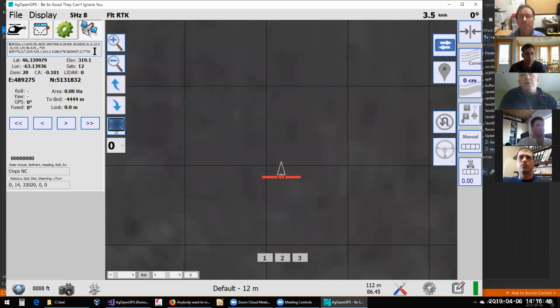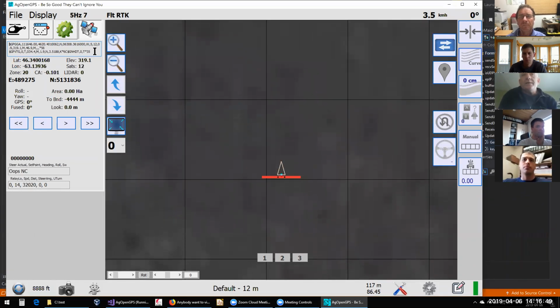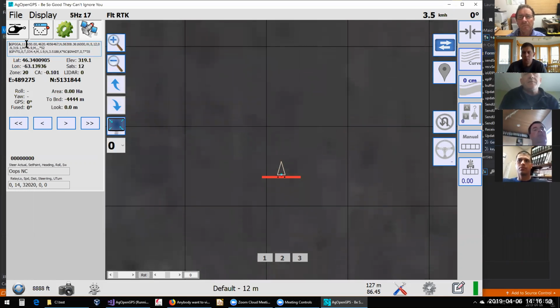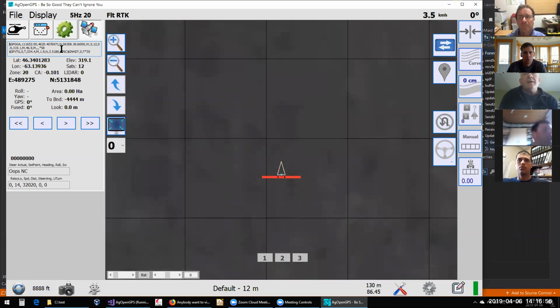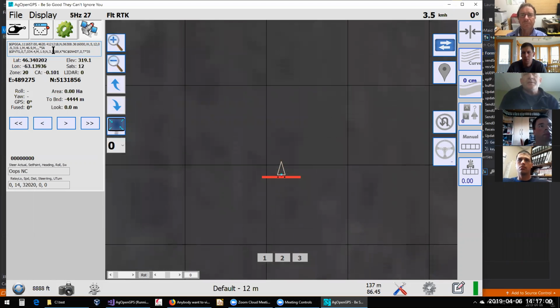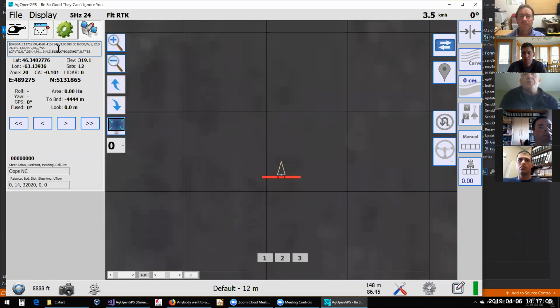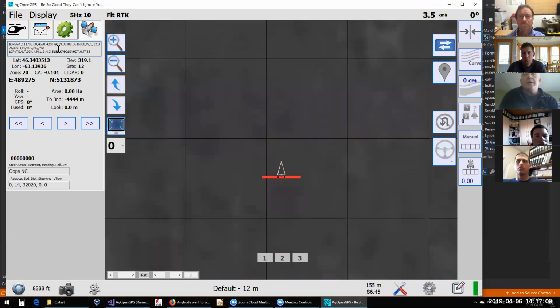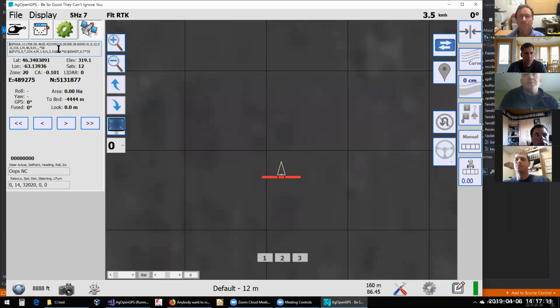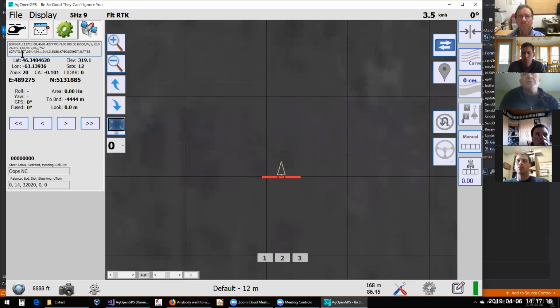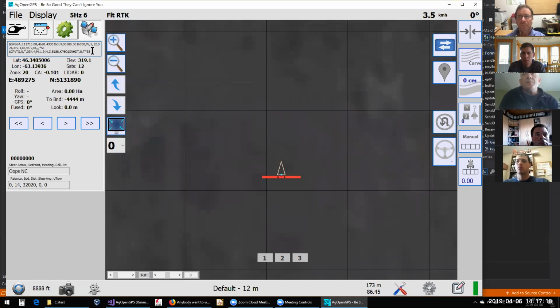But I think a lot of these GPS units put out so many sentences. That's an easy way to tell: if this isn't nice and smooth with no flickers, no dropped sentences, that sort of thing. If this is flickering and bouncing all over the place and it's blank and it goes half a sentence, then that's what your problem is. You can't get the data through fast enough. There's too much information there. The only reason we use VTG is for speed.